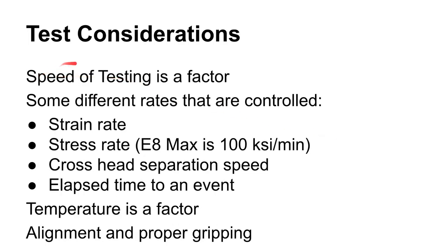All right, so some testing considerations. The speed can be a factor. So how quickly you apply this strain, you start pulling the parts apart, can make a difference. Okay, so the strain rate and/or the stress rate is going to be limited by the standard that you're testing to. This ASTM E8 limits the stress rate. Okay, and its limit, the max, is 100 KSI per minute. All right, and there are other ways of limiting and controlling that speed. Also, temperature is a factor, and the alignment and proper gripping is a factor.